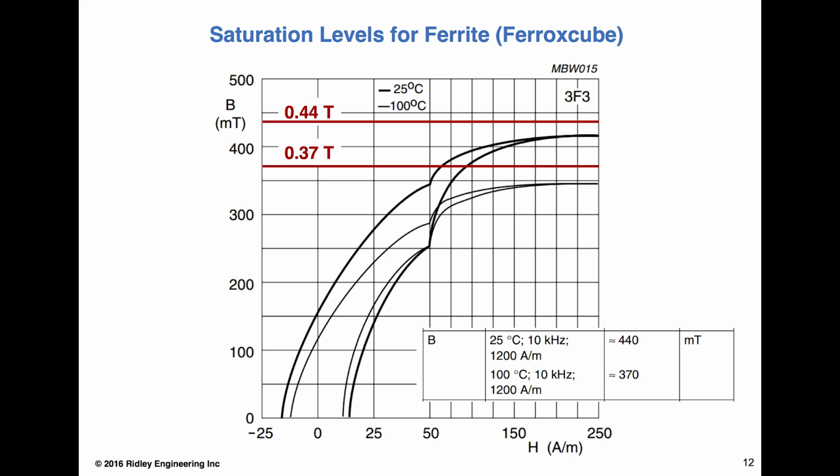It's funny when we have aerospace engineers in our courses, not all of them are aware of that anymore. It used to be the old-time designers, everybody knew that 0.25 number. The new designers, there's not always someone there to tell them. But it's just historical. It's just a conservative approximation to the 0.3. And of course, 0.3 is the industry conservative figure for what the saturation really might be.